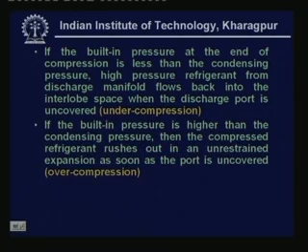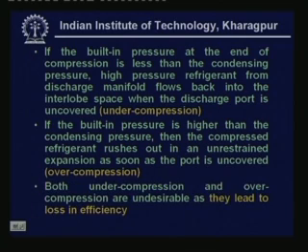So, as I said, if the built-in pressure is higher than the condensing pressure, then the compressed refrigerant rushes out in an unrestrained expansion as soon as the port is uncovered. Both under compression and over compression are undesirable as they lead to loss in efficiency.